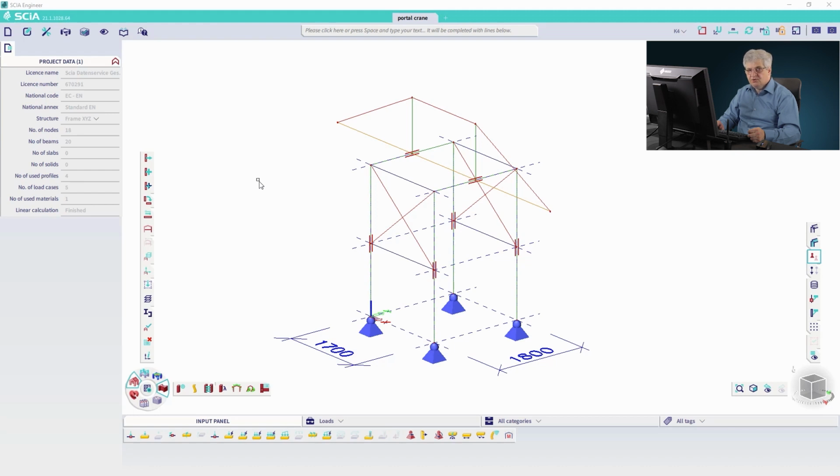These horizontal loads move the structure, they cause deformations and also bending moment, and from the rotation of the node and bending moment, we can calculate the stiffness of the node. We know also the bending stiffness of the member. If you compare it, then from these two formulas, you get the buckling length factor. The buckling length factor multiplied with the system length gives you the buckling length.